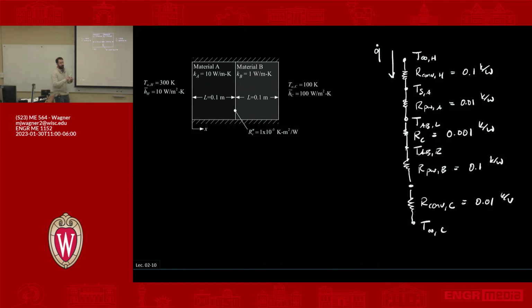So you should have heat flows labeled, any heat flows at any node labeled. You should have the correct topology, right? Every single resistance here is in series, so there's no way that heat can flow in two paths. It's all going in series all the way across. You have every resistance labeled and all the relevant temperatures labeled. Right? So I would get -1 because I didn't label at this point here.